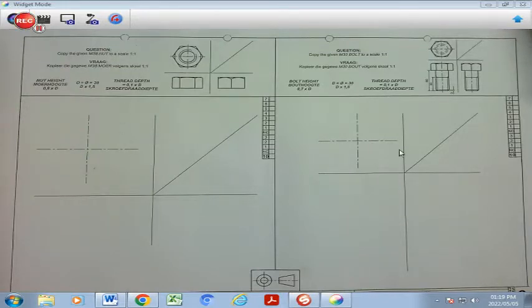So our first subsection of this page focuses on the construction of the nut. Now you will see that there's a straight part at the bottom here and a slightly curvy part at the top. There's a specific way of how we are going to draw this here as well as that part over there. Now if you look at this, the size of a bolt and a nut is normally given in metric, which is indicated by an M in front of the value. In this particular instance, if you look on your page, you will find that this nut is an M38.